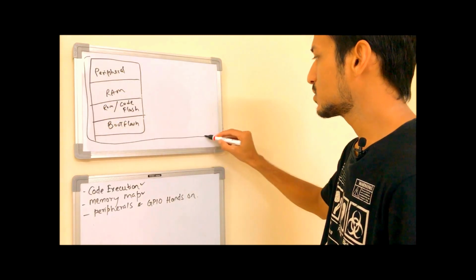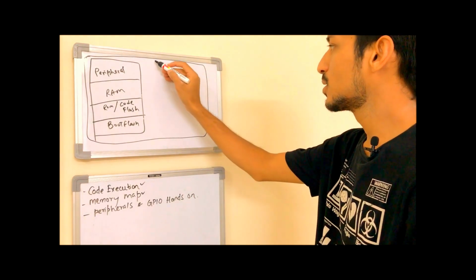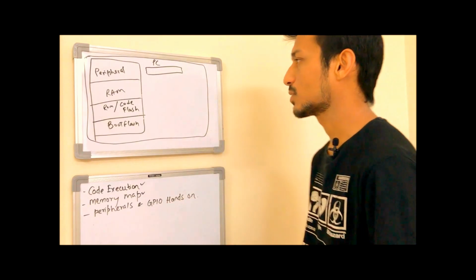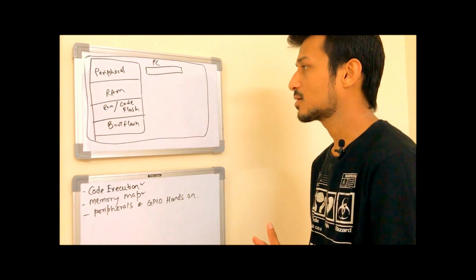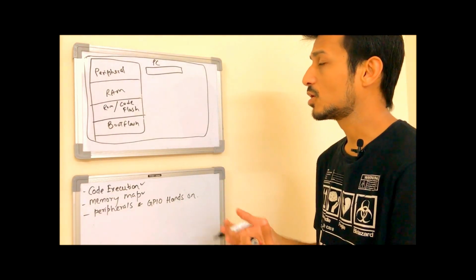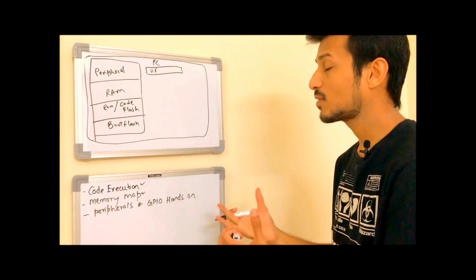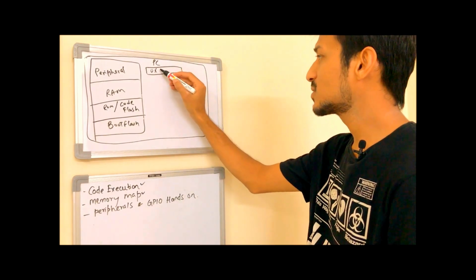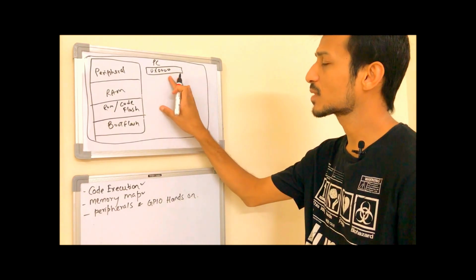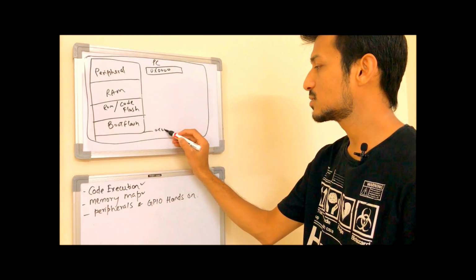All this is in a microcontroller, and inside a microcontroller or a processor you have a program counter register. Initially at startup, when you just power up a microcontroller, everything is 00, or everything can be loaded with FF. It depends on the architecture of the type of microcontroller you use. To make it simple, let's assume it's using a 16-bit address and everything at startup is 00, and this memory also starts at 0000.